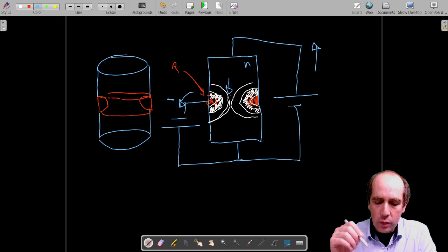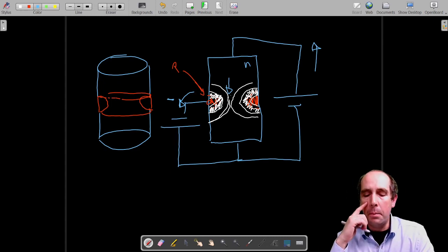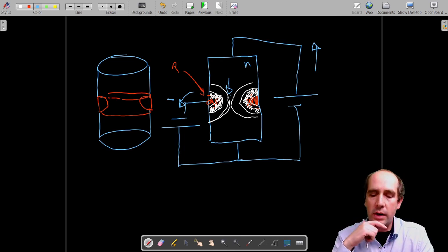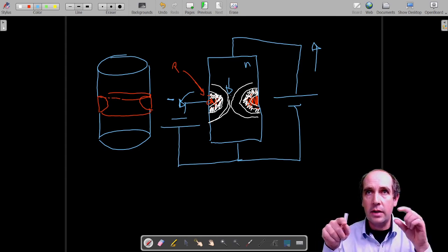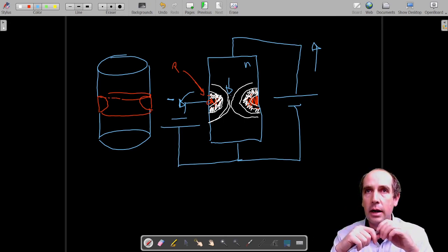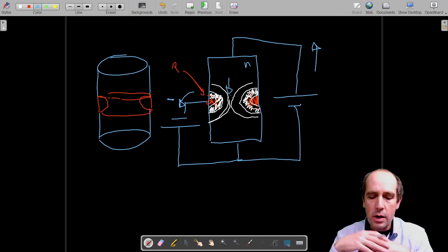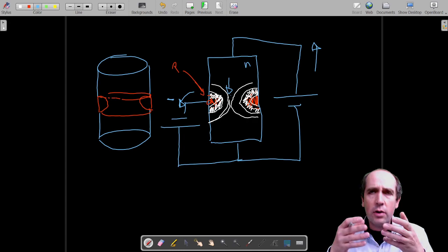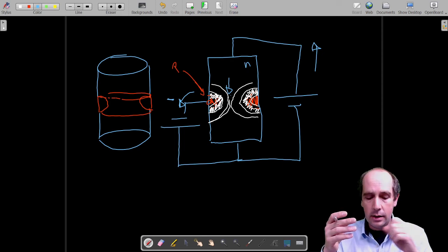But what we will achieve is a voltage controlled current flow, which is a little bit different to the bipolar transistor, the one we just discussed earlier, because that one is a current controlled current. So there is a little bit of current going through the base that controls the current going through the other two terminals. Well, here is a little bit of voltage but no current that controls the current that goes between the other two terminals. And this is the main difference between the bipolar transistor, the one that looks like a sandwich that we saw a few minutes ago, and this junction field effect transistor. And it's called field effect transistor because it's basically just controlled by the electric field and not by the current flowing in the case of the gate terminal.